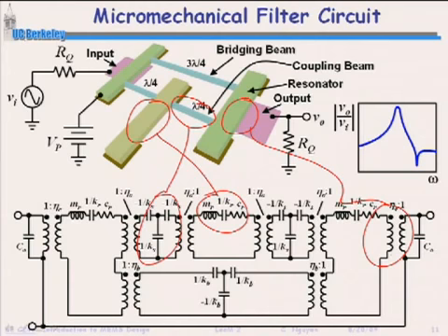So in this mechanical technology, you've got inductors, you've got capacitors, you've got resistors, you've got transformers. And transformers are something you do not have in conventional IC technologies as well. It's difficult to get a transformer. So there's a lot more you can design here just in this mechanical technology. And if you combine this then with transistors, you have a sea of flexibility in what types of design you can do.